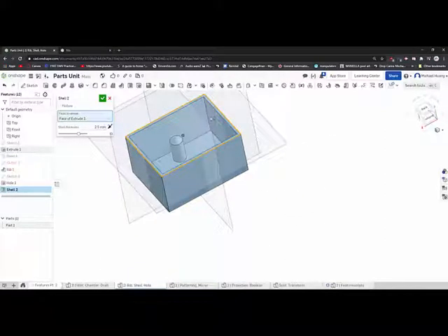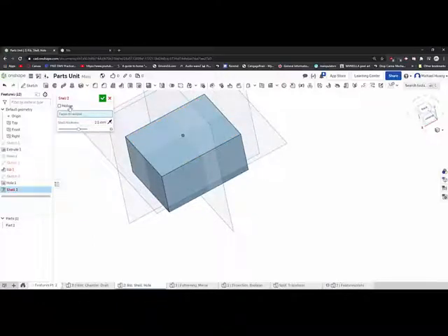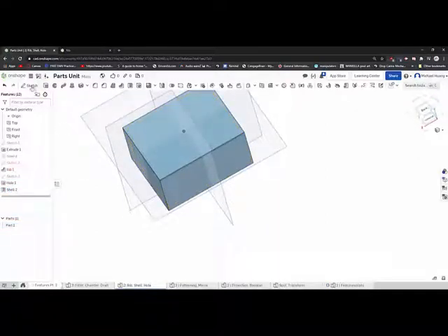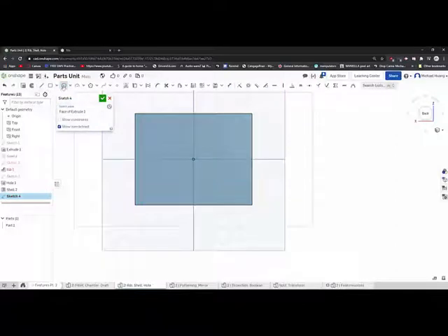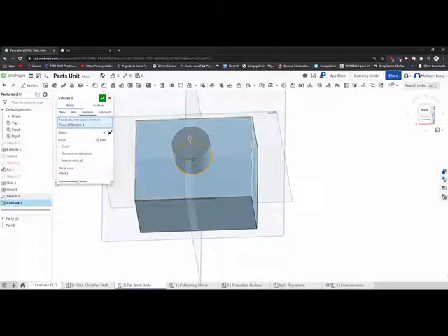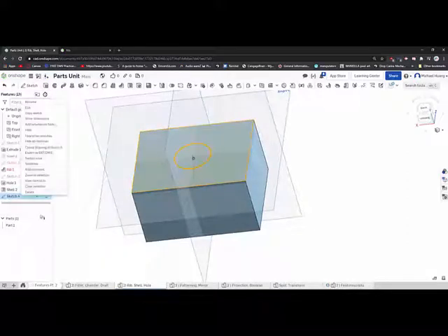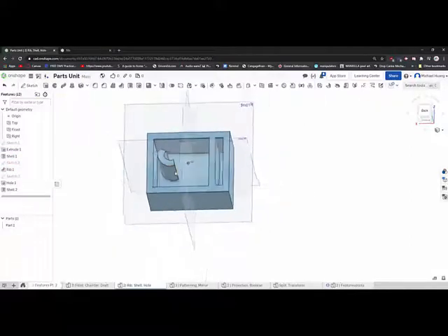All right, I can change the thickness of the walls and change the direction of the shell. Right, I can actually expand the material if I wanted to, or I can make it hollow. So parts, I click on the part, and you'll notice now, if I confirm it, and let's just say I make a sketch, it doesn't matter, I don't have to define this, make a remove extrusion. You'll see inside is hollow. Wow. Alright. The shell, unsuppressed. Okay, so there you go.